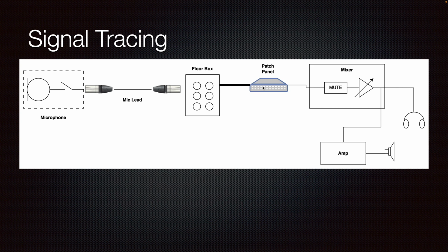Alternatively, I'd go over to the patch panel, and you can use the CT100 maybe in cable tester mode to actually do a test from there by putting a short into the appropriate floor box point. That's something you do in slower time, because really, to start with, you're just trying to get it working for the service. So you can test out that bit as well. Alternatively as well, if you're really stuck, let's put the CT100 as a signal source into the patch panel and see whether it turns up through that chain as well, just in case you think you might have a problem with that cable, or maybe even the patch panel. The patch panels occasionally fail.